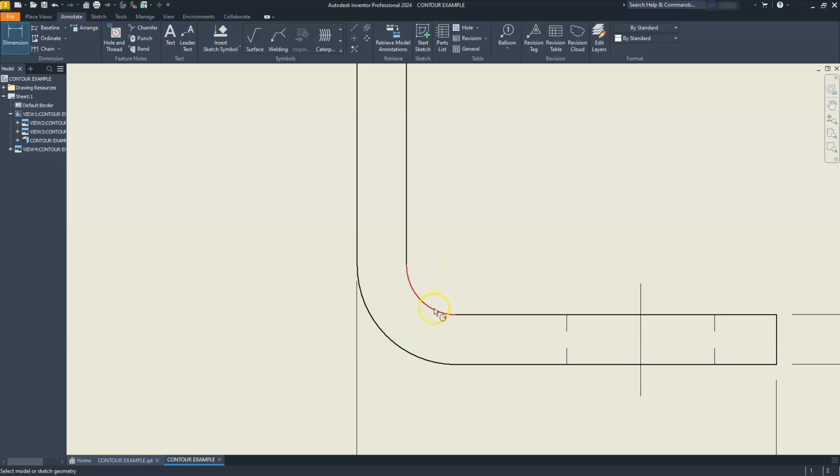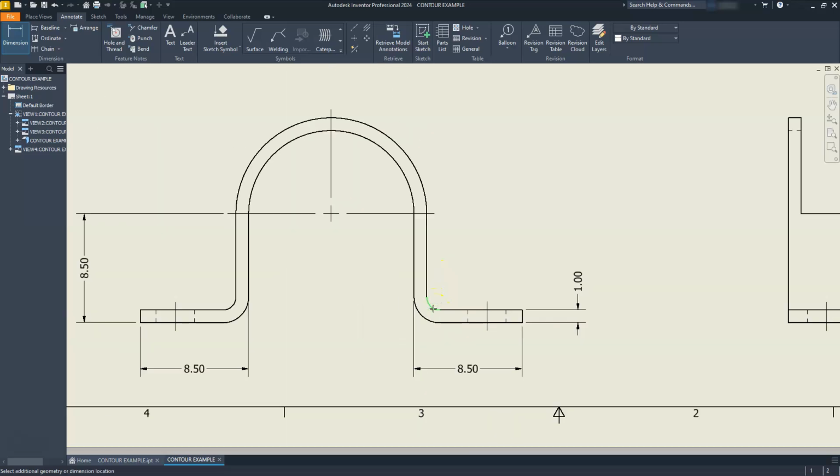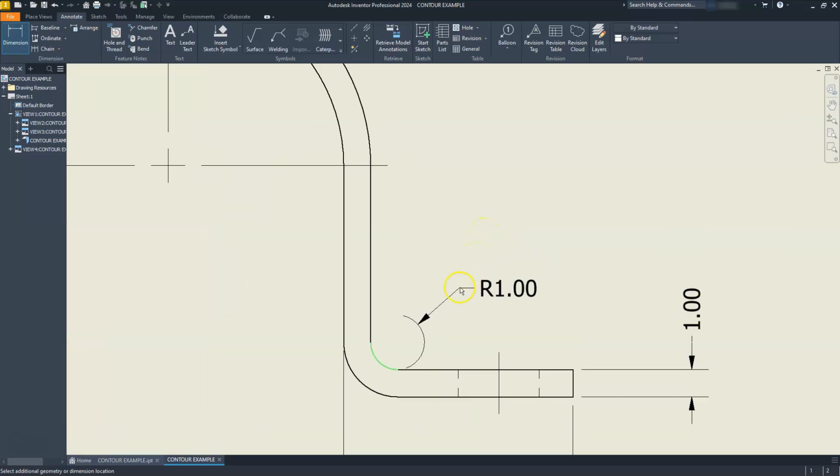Let's go ahead and put a radius dimension on this. I'm going to click here, and I zoomed in on purpose because sometimes you'll get this little icon here that kind of pops around like this, right? The way you fix that is that you come down and rotate to the inside of here, and once your arrowhead is on the inside, then you pull this out going this direction. Then do your left click here, and you can see that this number is wrong. Our drawing has a radius of 2. So I'm going to go ahead and fix that right now.